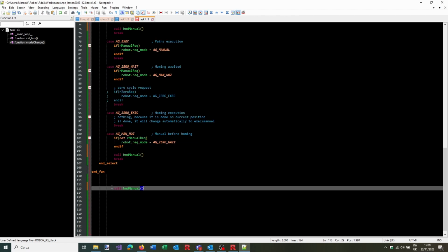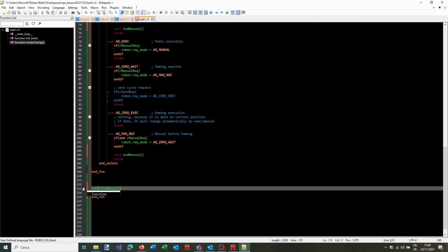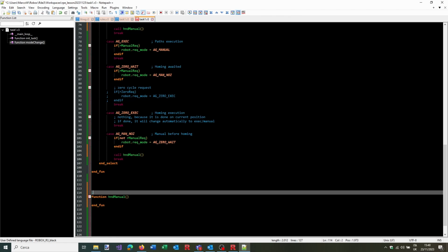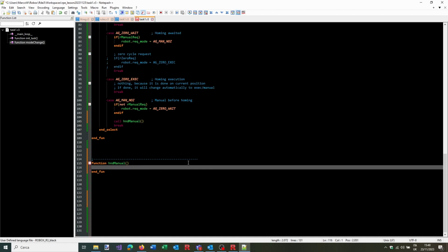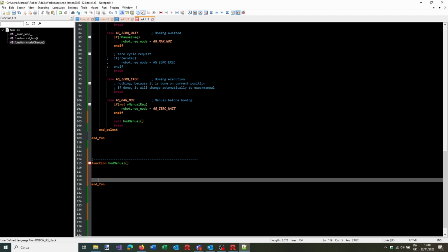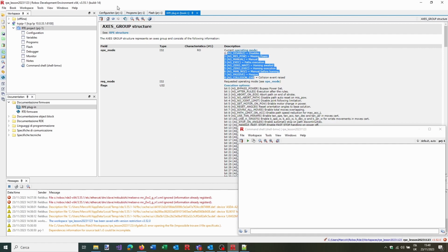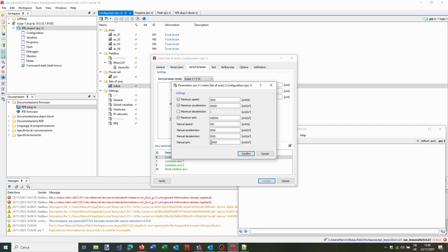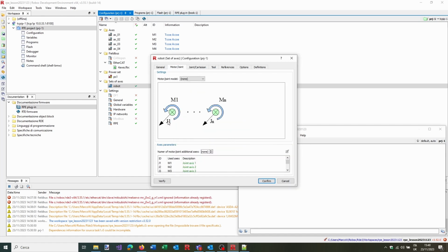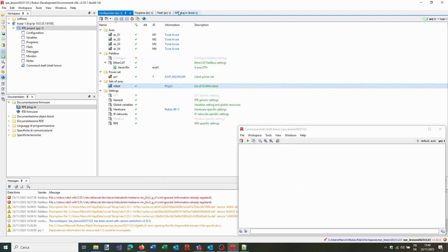And this function will be the same called here too. Now, let's go here and let's call it function. Let's put this nice comment in order to keep it more beautiful. Now let's have more empty lines here below. And here, for example, we would like to set the jog commands. Now, since we already defined the robot, and here we have the manual speed, acceleration, deceleration and jerk, both for the Cartesian mode and for the joint mode. We just need to set the commands.